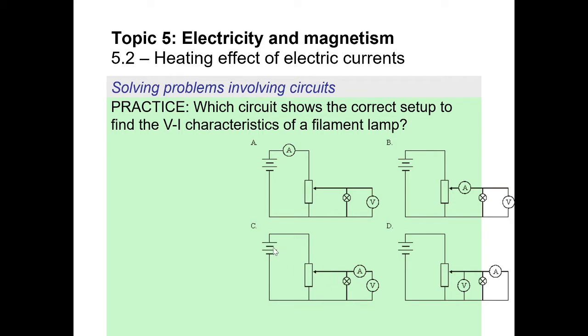All right, for C, we've got the current coming out. When it gets to this resistor, there's a junction, it splits, so some of the current goes to the right, some of the current continues down through this resistor. The current that turns right, when it gets to this junction right here, is not going to go any further, so it's not going to split again and go towards the ammeter, because ideally this voltmeter has infinite resistance. It's like there's a lot of traffic here and the traffic just doesn't move, not even 1 centimeter a second. So no electron is going to go straight, it's going to immediately turn right.